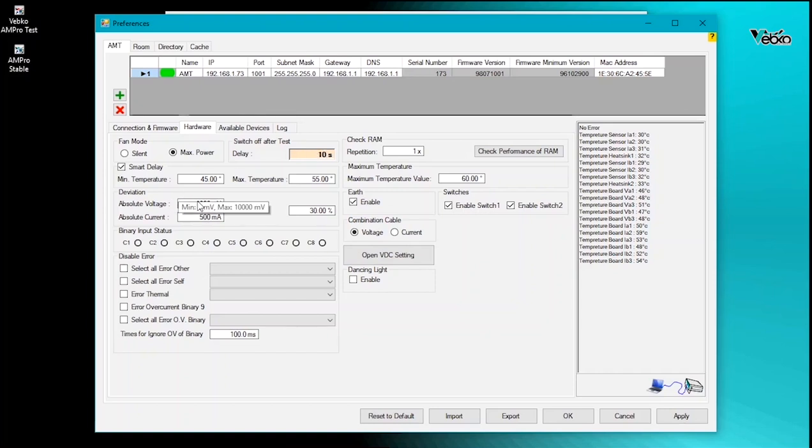In the Deviation section, the reporting conditions for other errors can be specified. By default, it is specified in the software that if the actual voltage of the device added to the value specified in the software exceeds 4 volts, or the current difference passes 500 mA, the other error should be displayed. In the Relative section, this value is specified as a percentage of the value specified in the test. In the actual operating mode, the device uses the highest value among these two for the error message.